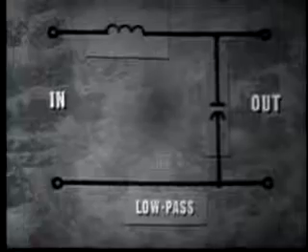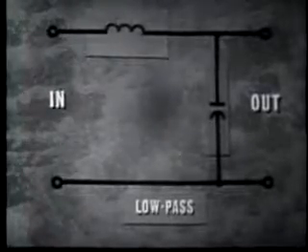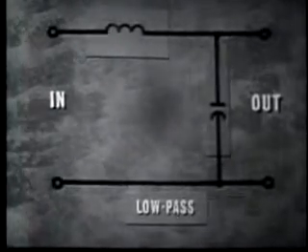It offers a large impedance to low frequencies and thus develops a large voltage across it. Since that output is taken across the capacitor, the output voltage is large at low frequencies. At high frequencies, its impedance is small and it does not develop a suitable output voltage. No output at high frequencies.